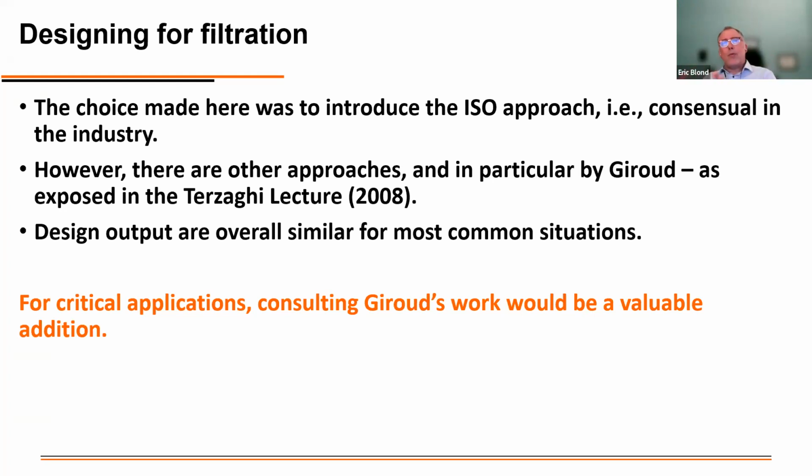But at the end, when a project requires an in-depth investigation of the filtration phenomenon and the design of a filter, I highly recommend to consult Giroud's work as a highly valuable addition to complete the design for filtration.